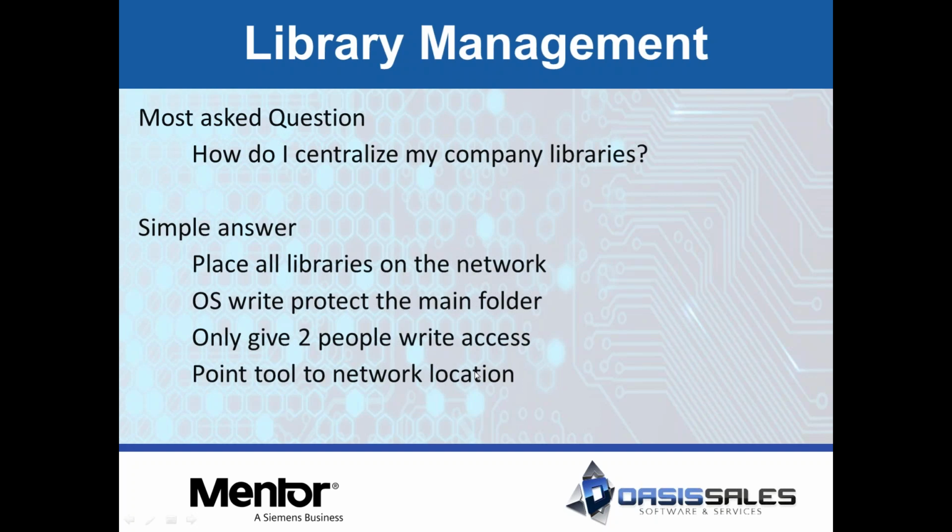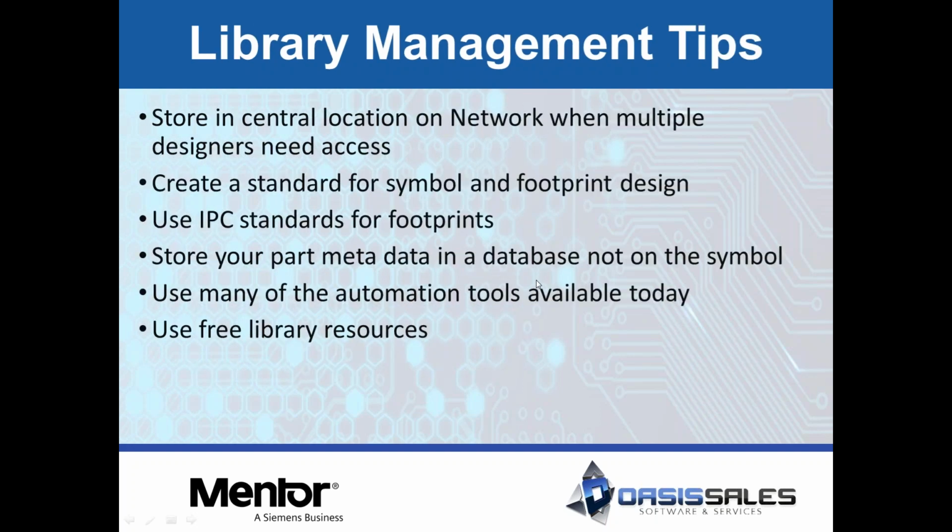And then point your tool to that network location. Every layout and schematic tool out there should have a way to point to libraries that are not necessarily on your hard drive. If not, look at upgrading to a tool that does have that capability. I know DX Designer, PADS, any of the Mentor products, you can point to any location on a network or even a web server in some cases for library content. So this is, again, one of the biggest questions that a lot of people ask, and it's a very simple thing to do. People just don't realize that storing stuff on the network is really what a centralized library is, per se.